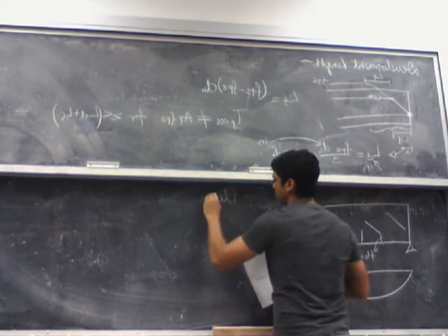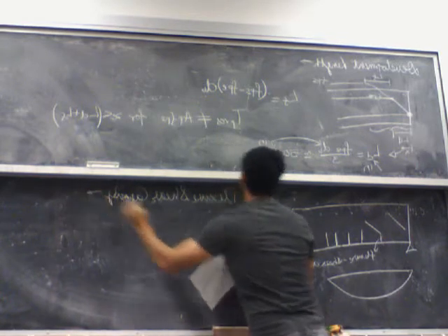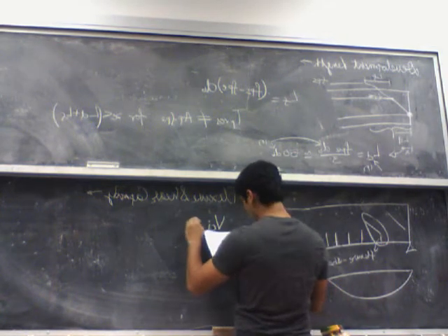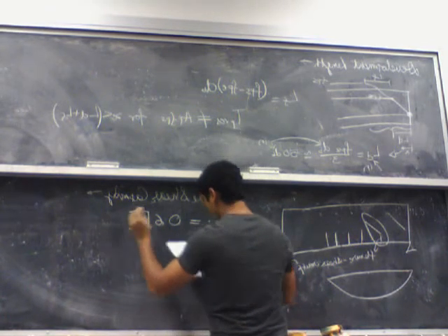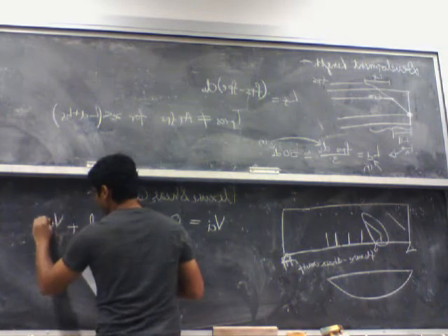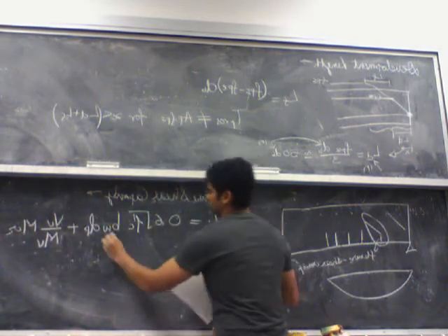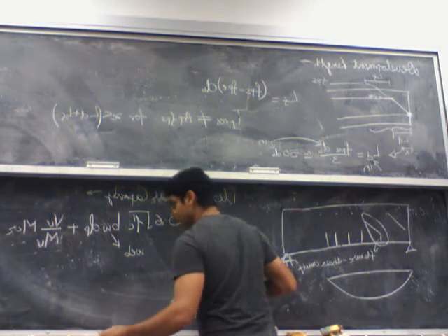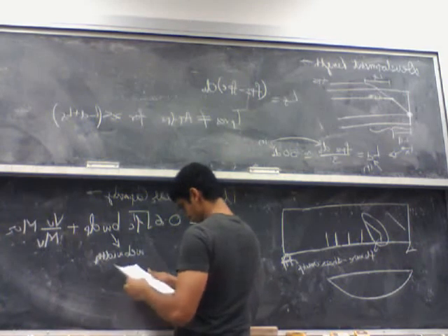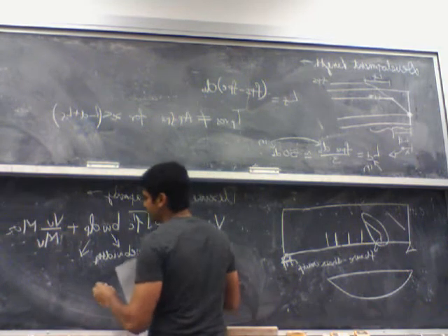So for the flexure shear capacity, that is these cracks, the shear capacity of the concrete is given by 0.6 square root f'c b_w d_p plus V_u over M_u times M_cr, where this b_w is the web width, and this d_p again is the distance from the compression face to the centroid of the prestressing strand.